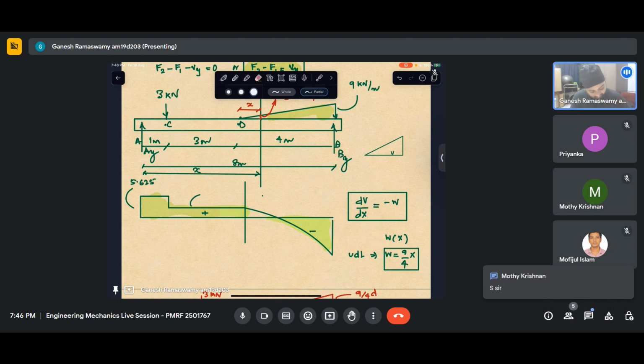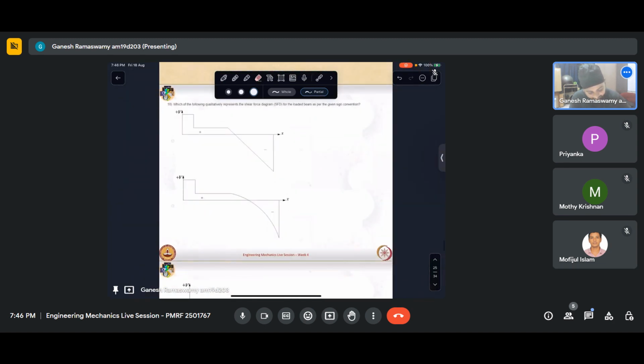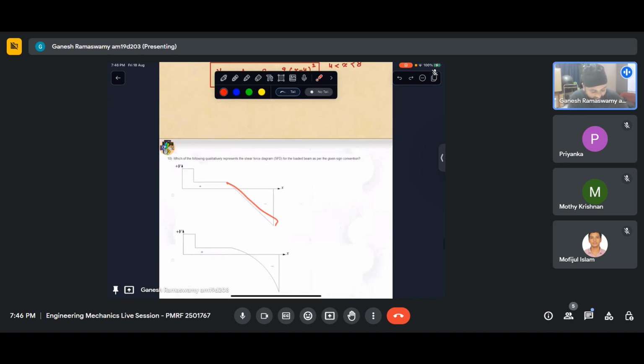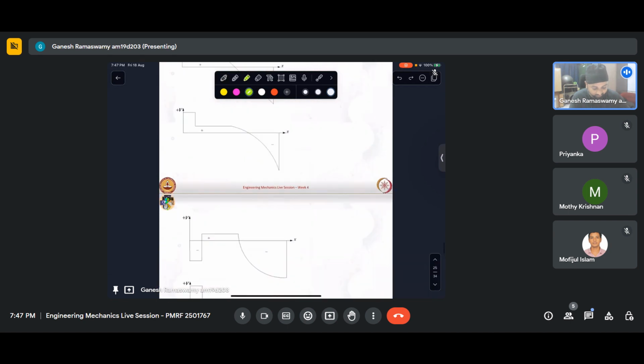All right. In such a case, let us look at the options here. Now, this has a linear variation. We can clearly see when would this be if we had a beam, the same beam, which was like that, and a load applied like that, and then we had a UDL. If a UDL were applied, then this case would hold because it has a linear variation. Right now it is having a quadratic variation. So essentially, this is correct.